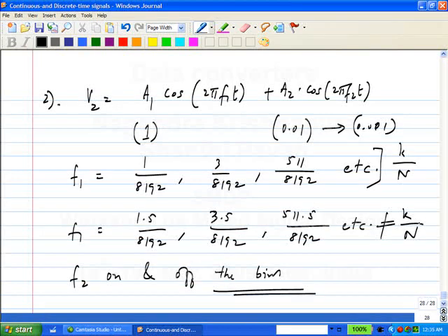Now, if I have, let's say, 0.01, and if I plot a sinusoid, even the 0.01 I can't make out in the time domain, right? If I have a sinusoid and a small harmonic content on top of it, I will not be able to make out at all the small different frequency content. But in the frequency domain you can, because you have the logarithmic scale. You can even distinguish something that is 1 volt and something that is 1 microvolt. That is the other advantage of the frequency domain. It separates the frequencies and you can distinguish widely varying strengths.